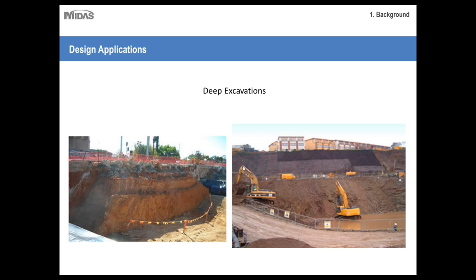And then naturally, deep excavations. As you can see, whenever excavations for foundations are created, slopes are a natural part of creating these foundations. Until these foundations are built, the stability of these slopes needs to be checked and designed for. Oftentimes there are tiebacks or soil nails that are driven into these slopes to support them.